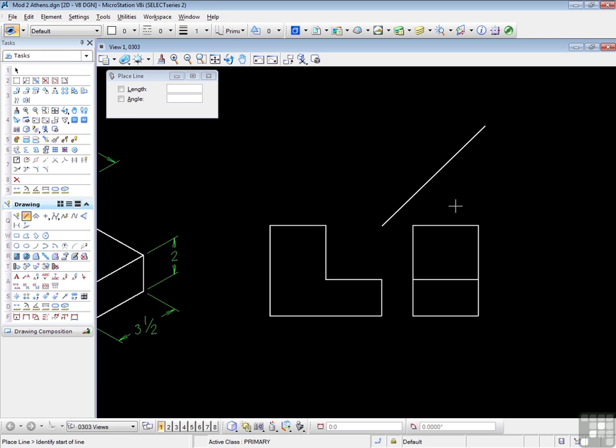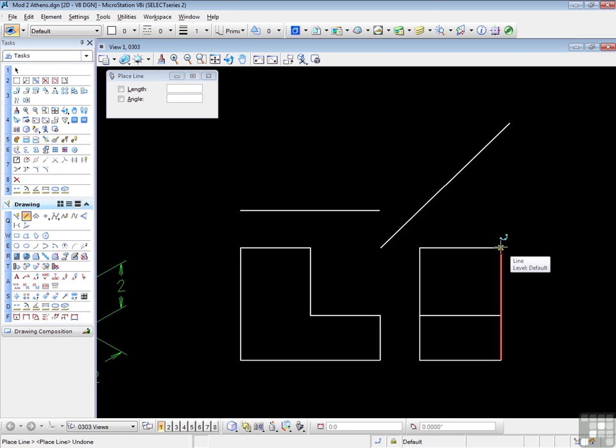Now let's go across to the plan view. I'm going to use the diagonal line as you do in normal manual drafting, take the information from the right side view across to the plan view. Now I'm going to find the right side of the right side view. So F11 and the O key, up, enter, and N, O key, come across, enter for smart lock, find that point there, left click, come across, enter, find that point there, and we're away. Now it's simply a matter of connecting these two ends, and we have the plan view.